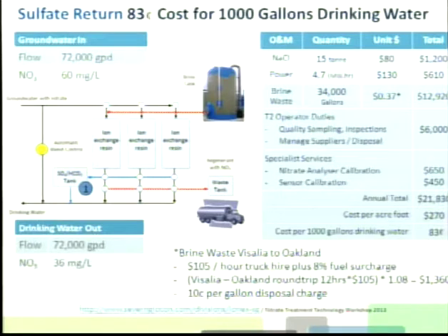But the real kicker, if you're at the back end of Visalia, is that even at 0.12% of brine, you're still looking at 7 to 10 tankers trucking that waste away from you to go somewhere. And the fundamental problem with brine disposal, if you imagine a 0.5%, it's going to be much higher than this, is this little calculation down the bottom from Advanced Chemical Transport, fairly typical for me.